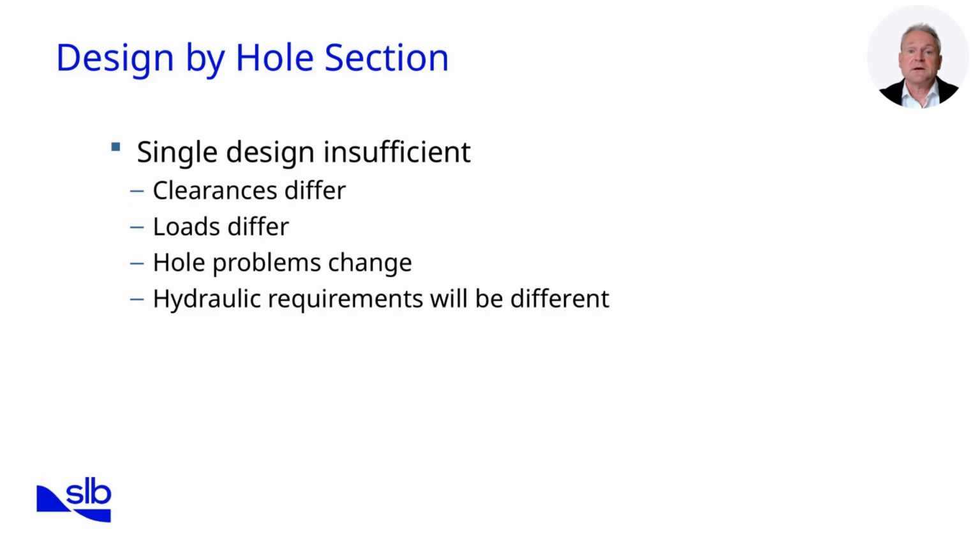One of the most practical approaches in drill string design is to break the well into hole sections and design each part of the string accordingly. Shallow hole sections often face challenges of buckling, bending, and vibration. In these intervals, stiff drill collars and stabilizers are chosen to minimize stress.